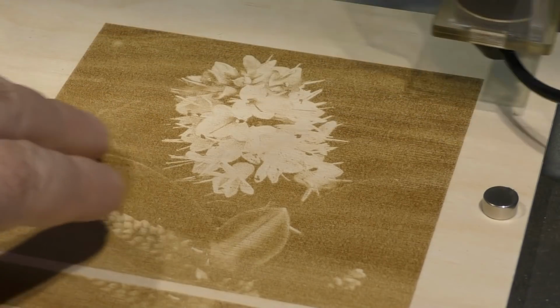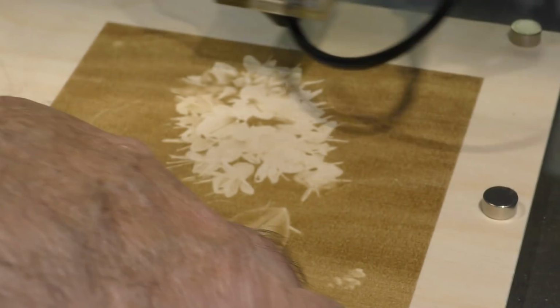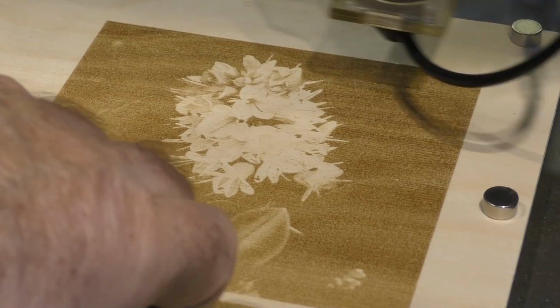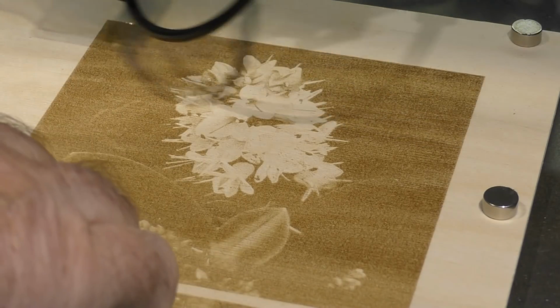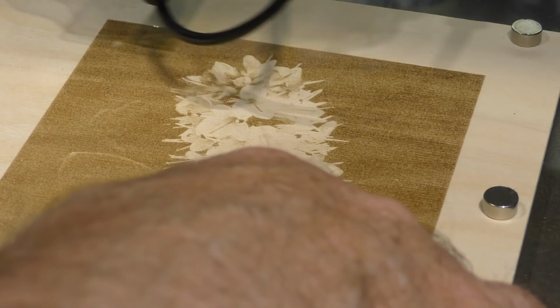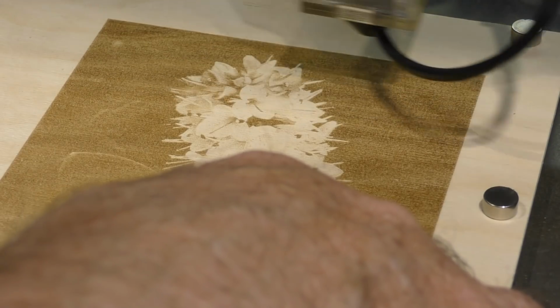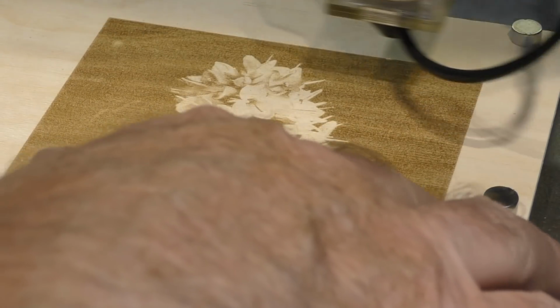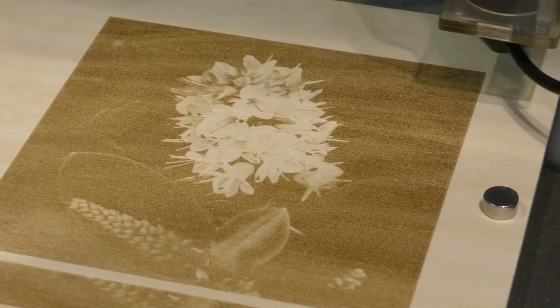So as I get up here, I very carefully eased the focal distance at a point here. You might be able to see a line across there, and I can feel that it is slightly rougher here than it is here. In other words, the focus was just very slightly out. So as I change the focus, and in fact I decrease the focus, you'll see there's a slight change in the colour. And there's also a slight change in the texture of the wood, the finish. So I've got it more or less correct now, whereas I didn't have it quite right to start with.